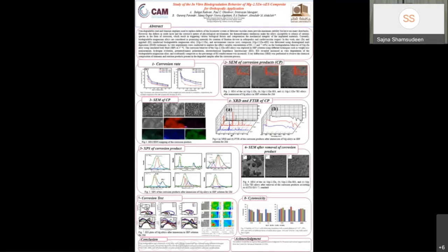Biomaterial alloys such as titanium and stainless steel are broadly used as implants. However, these metallic implants are much stiffer than natural bone due to the mismatch in modulus between the bone and the permanent implant. A stress shielding effect could accordingly happen where metallic parts are in contact with the bone, inducing bone resorption, decreasing implant stability, and finally causing failure.